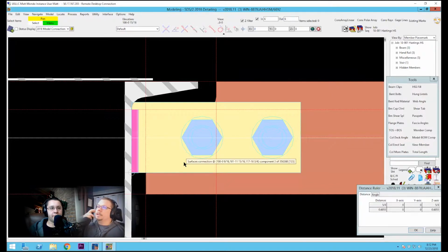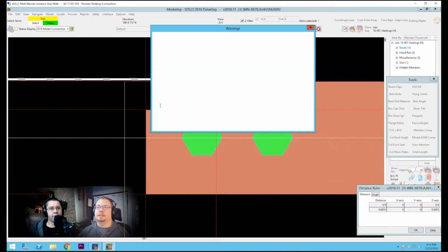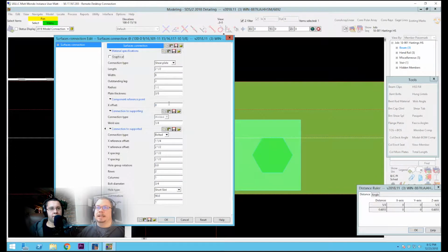Right. Now, there's a couple things that you should be aware of when you're working with this, and I'll get into explaining the axis in just a moment. So you saw me change that X offset, but if you open it back up, you see it's set back to 0. This is a per use, per opening of the edit screen sort of tool. It will always go back to 0 when you're done. So if I were to, say, go back in and minus 5/8, it will just move it down and then leave it back at 0. So this is how much you've adjusted it that time.